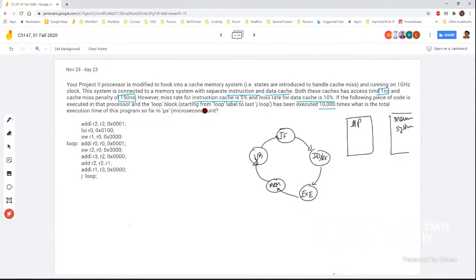The view of the microprocessor is that it supplies the address and bidirectional data, and it also receives the signal wait. If it is wait, that means data is not sent back from the memory system. So with that respect, we need to add an additional cycle, conditional on wait equals 1.